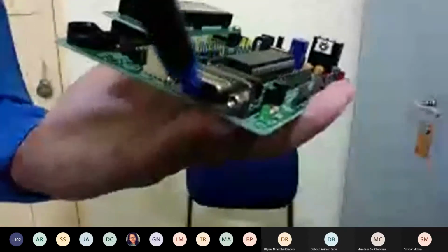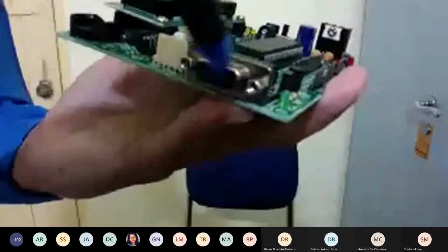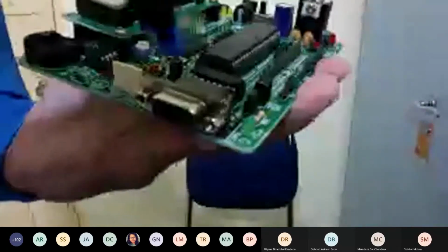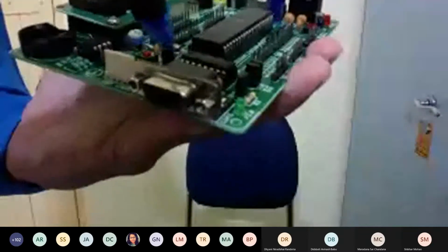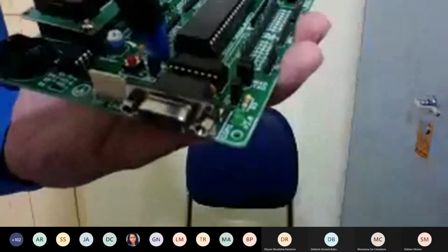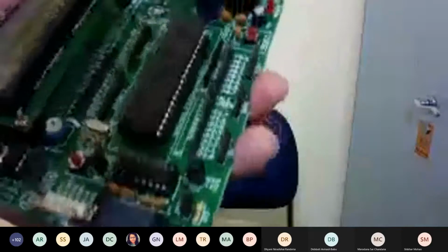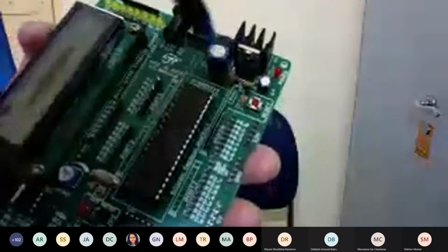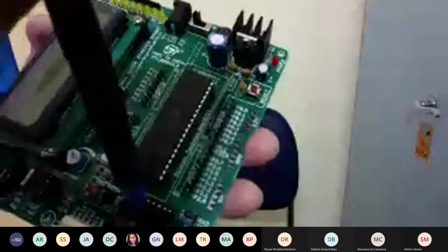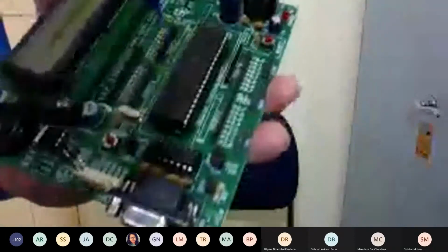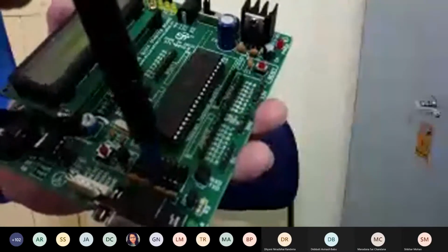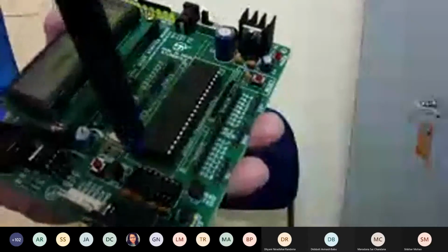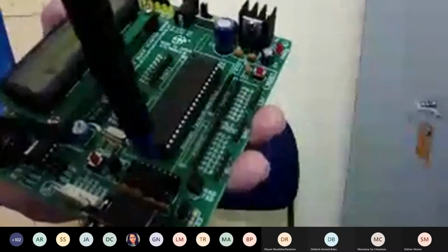That's why you get to see this 9-pin D connector, and it operates at plus and minus 9 volt for logic 0 and 1. So logic 0 means plus 9 volt and logic 1 means minus 9 volt. But here the voltage regulator gives a single supply, so 0 volt and 5 volt are provided as power supply. You need minus and plus voltages which are beyond that. Plus 9 is obviously higher than 5, and minus 9 is definitely not present. So it takes 5 volt and converts it into plus 9 and minus 9 volt.